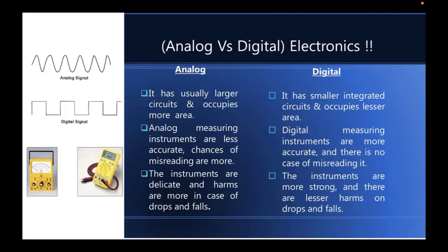But from the electronic perspective, what I can easily mention is the term we introduced in the previous lecture with the analog noise analysis, the term noise immunity. So the noise immunity in digital electronics is much, much, much higher than the noise immunity for analog circuits. And conceptually, you can understand that very easily when you compare an analog continuous motion on the y-axis with discrete levels on the y-axis for a digital signal.